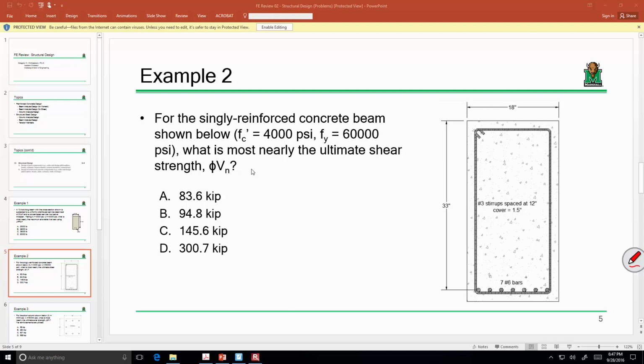That's the whole point, so that you understand this. If you remember, for shear we really treat it like an equilibrium, a sum of forces in the y direction. We have a shear contribution from the concrete and a shear contribution from the steel. How do we calculate the shear contribution from the concrete, the V sub C? 2 times square root of FC prime times BWD. It's on the second page, about right in the middle, where it says beams shear.